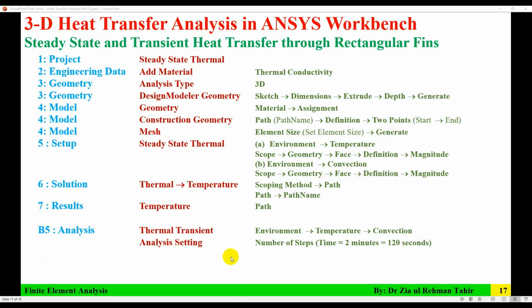So as this solution procedure is going to change, and for transient thermal, density and specific heat capacity are also required, so we need to change the material here and add those properties.